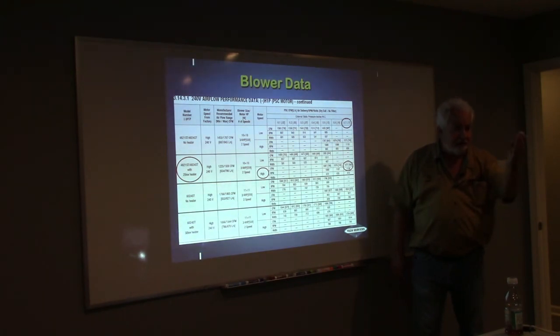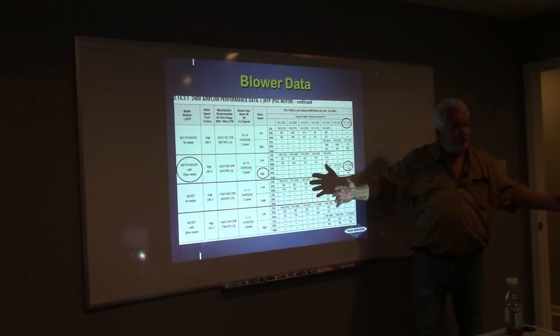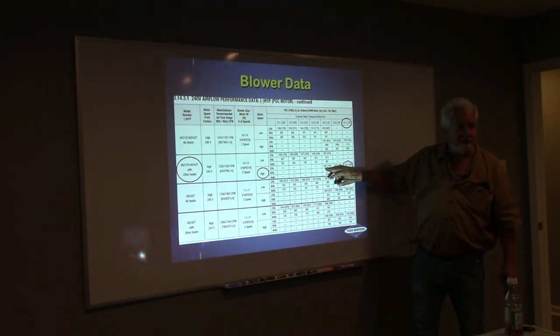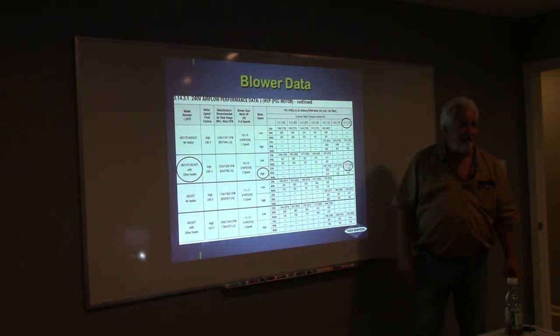It's on the return side. So if I make the return air larger, I get a better filter, I do something on the return side, what's going to happen to the static? It's going to drop back here. And what if I get it back to a 0.5 on here? What's going to happen to my CFM? I'm going to have a blower then. I've got 1687 then, right? How am I doing on a 4 ton now? Sweet. Does that make sense?